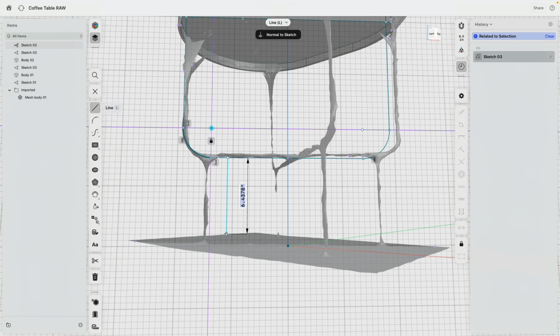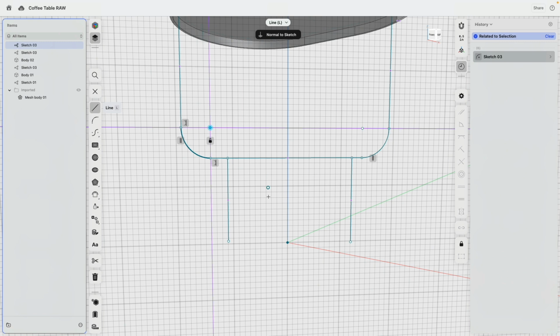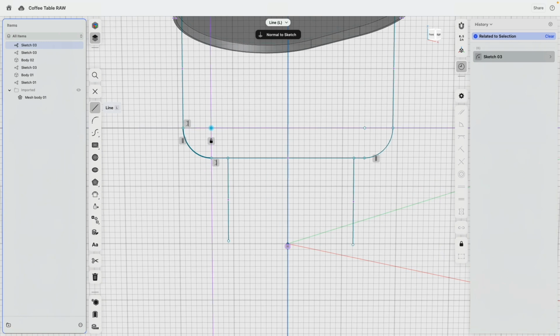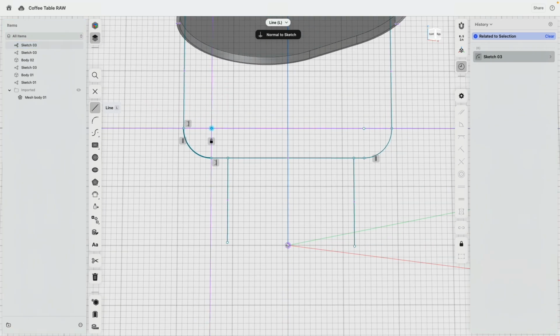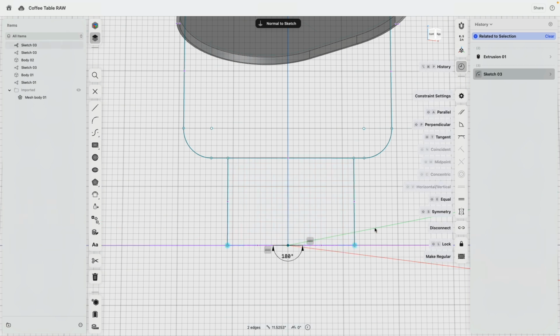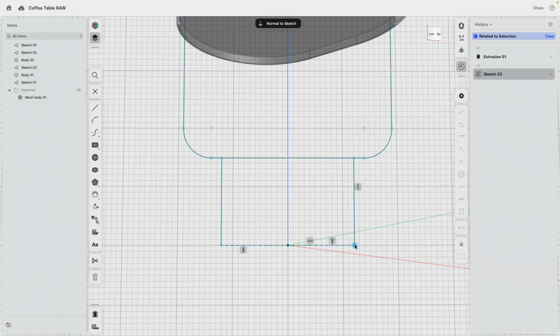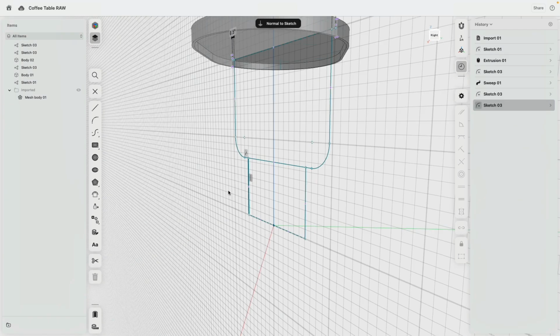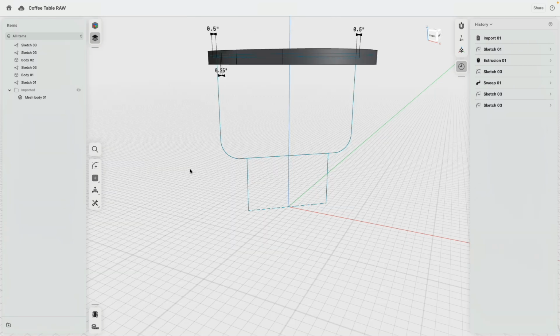So somewhere here, a line down, and we have the same also somewhere here. Escape. I'm going to hide this one more time. What I would like to do is from there to there, and from there to there. And these lines are horizontal, vertical. These two lines are construction and equal. And because they're equal, you see I'm moving the two lines equally apart. Little drafting trick. Perfect. So most is actually done.